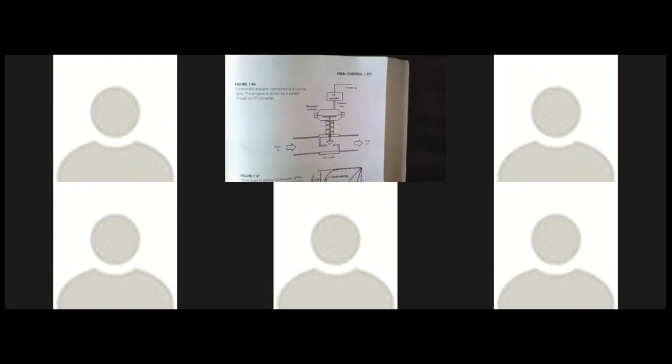So when you enter the shower, you say, today I want 1 gallon per minute. And tomorrow you want 2 gallons per minute. So if you want a really fancy shower, you can do that by having a PID controller control the flow of your shower. The final control element will be this valve. It will control the flow of the shower.